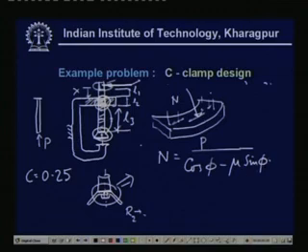So the contribution of this term is very small, and if phi is very small, then cosine phi is almost equal to 1. So this is very much equal to P. Now, this amount of normal force is distributed, acting uniformly over the thread, so it develops what is known as the bearing pressure on the thread. Let us look at the bearing pressure now.